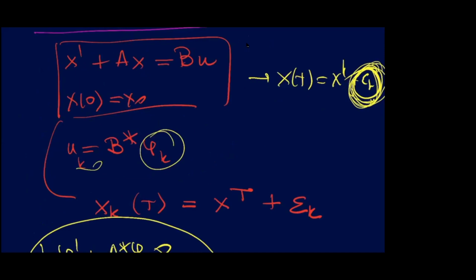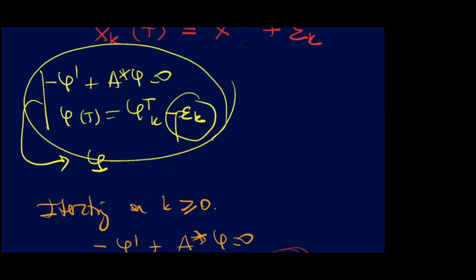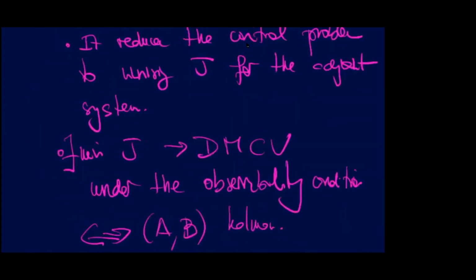And this is precisely the duality of Wiener between control and communication. They go together, and here you see it. Even when you are dealing with these linear finite dimensional systems, if you try to operate in an intuitive manner, your intuition fails because there is a point where you say, well, I have an error, but what does it mean in terms of the improvement of the control? You see that when you write this gradient descent algorithm on the adjoint, you can have a very precise formula of how you have to do it. But it's never easy because you have to go through the adjoint and correct actually your guess at time capital T for the adjoint.